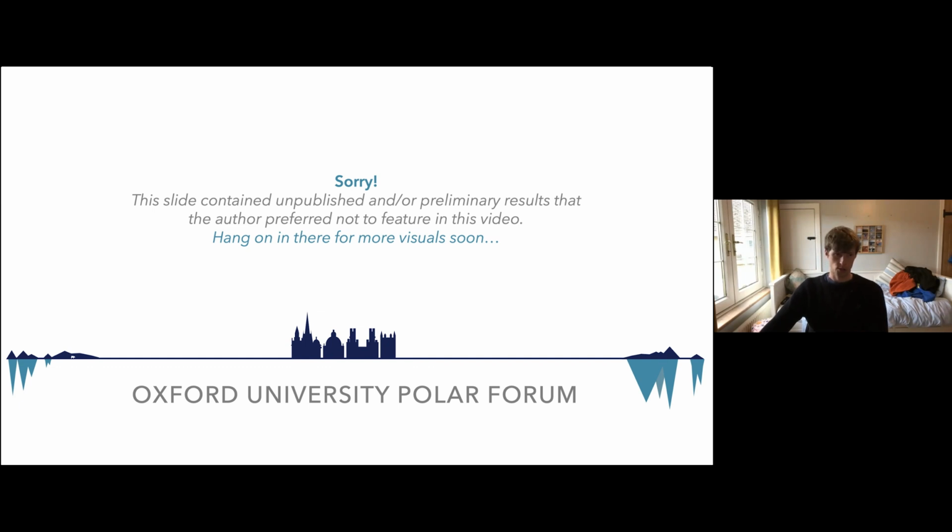The fact that we have icequakes lower than this bottom line is not a worry. That's just one measurement at an ice stream. And in fact, it's actually very difficult to get this measurement out. These are some of the few measurements we do have of an in situ shear modulus of a till in an ice stream. So we can see in some cases, these shear moduli go very low, 2 orders of magnitude lower than the shear modulus of the ice.